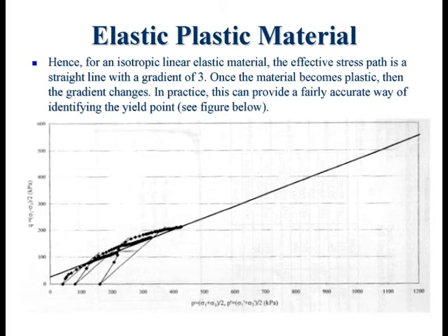Alright? So basically, the first thing to interpret is to separate the total stress path from the effective stress path. And there are three sets of test results over here. Each set of test results consists of one total stress and one effective stress path. And the total stress path, the way you want to look, one of the first things that will distinguish you is this.